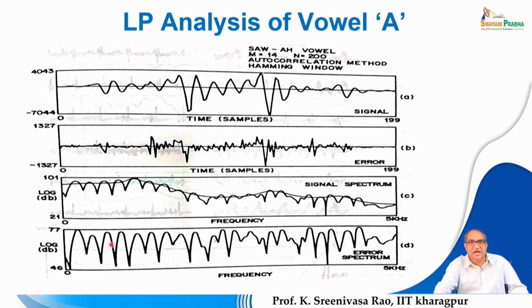Flat means that the overall envelope seems to be flat, right, but the ripples are basically due to the periodicity offered by the error signal, because here you can see this is the voiced segment. So, it is obtained by the periodic excitation. This periodic excitation will be reflected as ripples, because the periodicity can be reflected as harmonics in the spectrum.